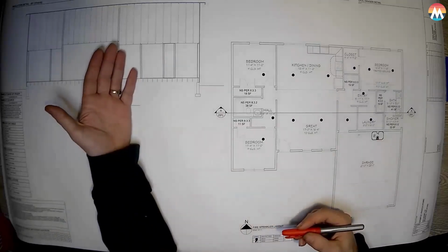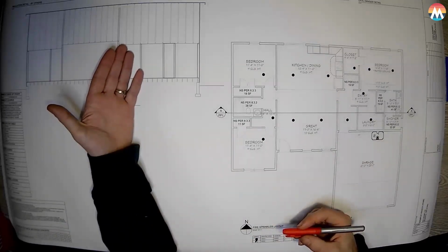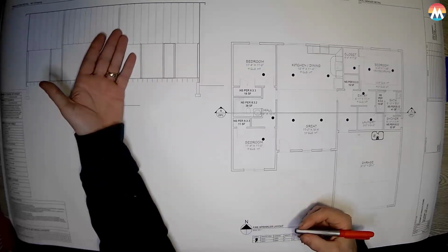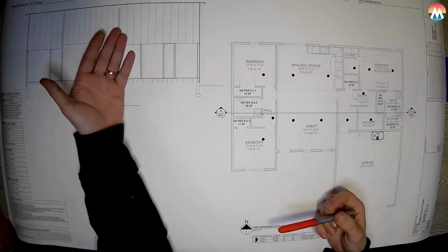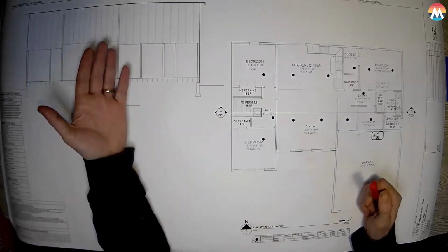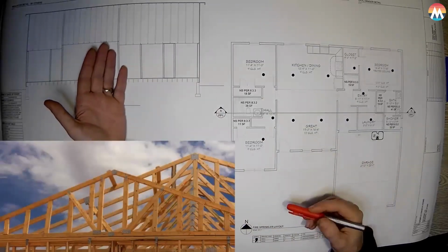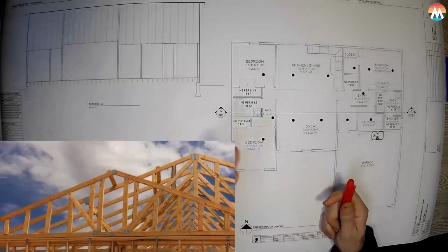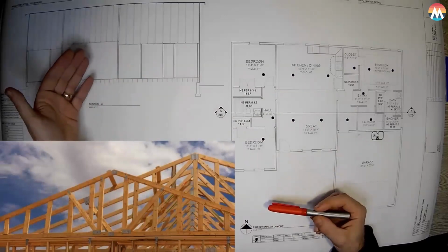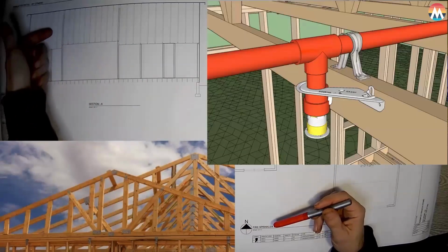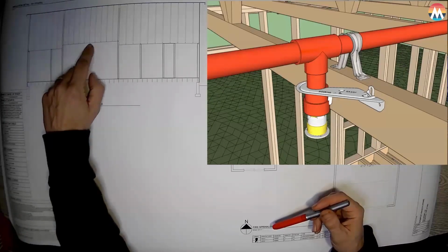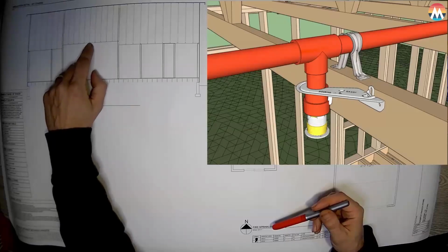Many of you, if you're new to construction, may not understand this, but this ceiling or the roof system is built with a common building system here in the Pacific Northwest. They're manufactured roof trusses, and they're built out of 2x4 and they're spaced 2 foot on center. The attic space is basically wide open, and it's easiest for us to travel through this space and rest on the top of the bottom chord.